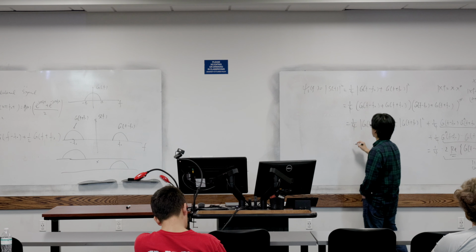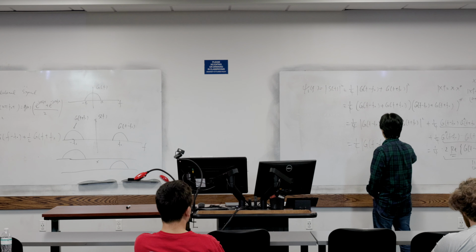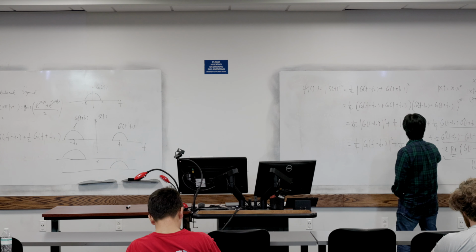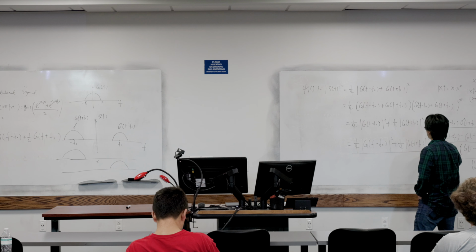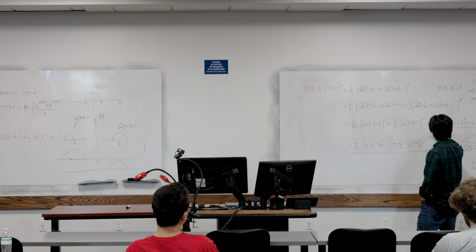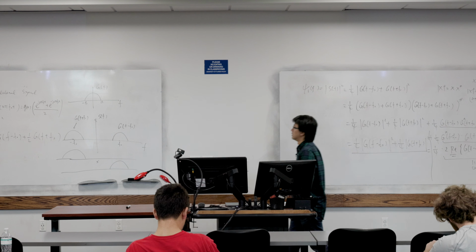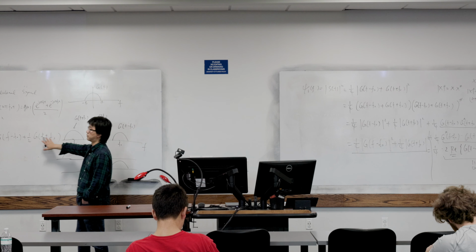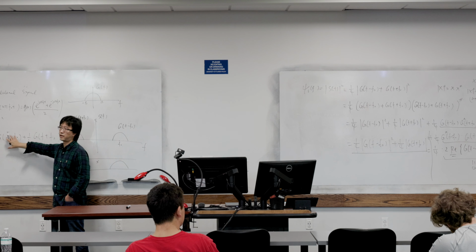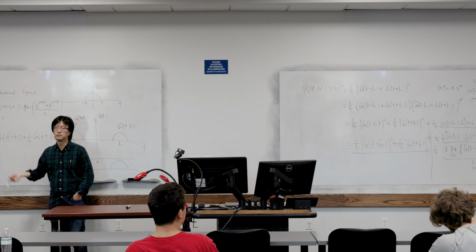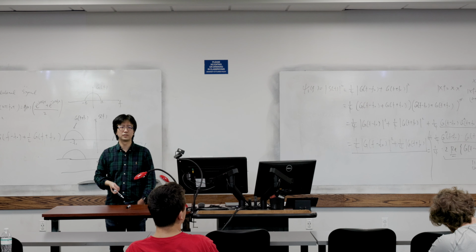So only this is left. So basically we can comfortably write the power spectrum, the energy spectrum density, is nothing but this guy. Right, this is our final answer, and we don't have this. Which is very nice, right? Because if you see, this is the Fourier transform. The energy spectrum density is nothing but the square of this guy add the square of this guy. That's it. Right, it's very simple. So any questions so far?